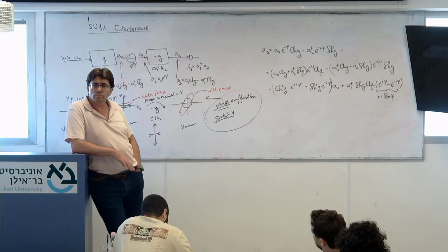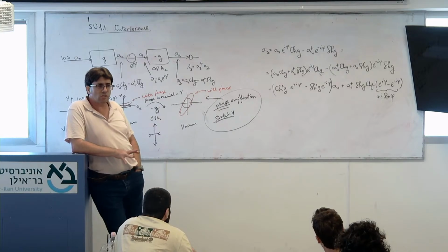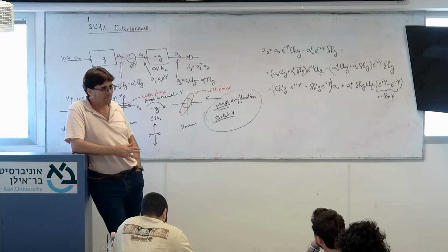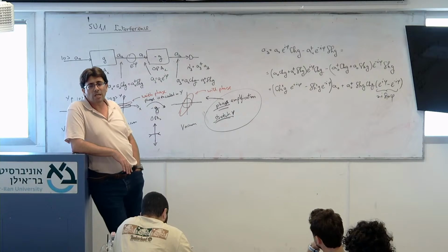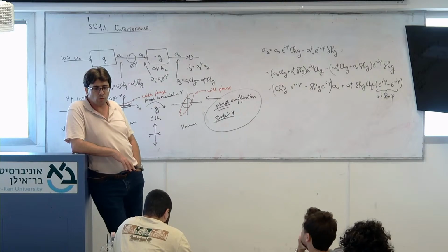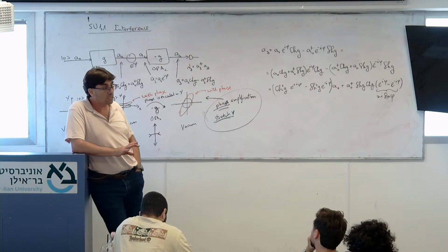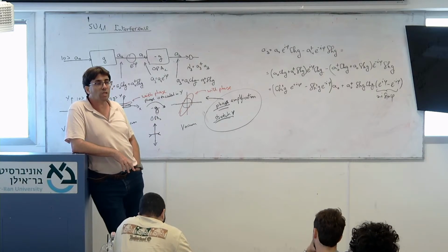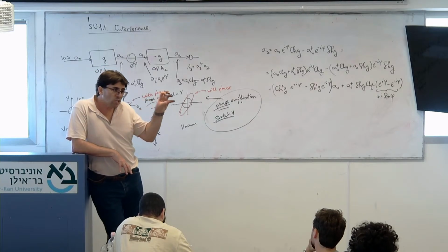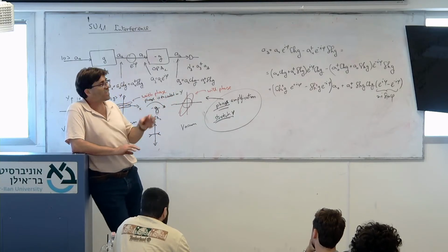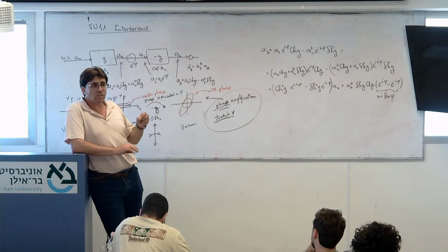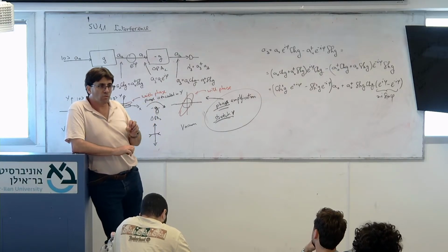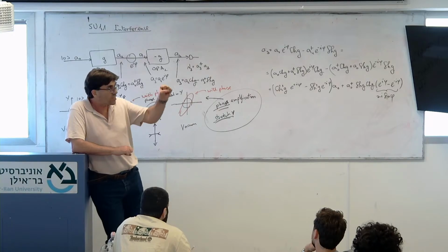So first, this is something that every good engineer knows. And some of you are good engineers, or maybe one day. If you want to measure a small signal, first of all, use an amplifier and put that amplifier as close as you can. If you have an antenna that brings in a very small signal, you put the very first amplifier very close to the antenna.